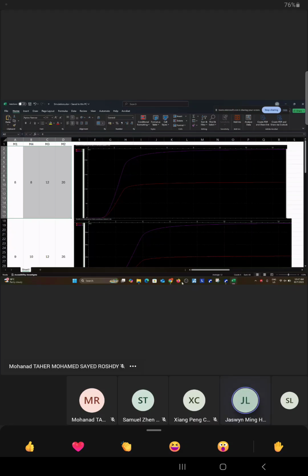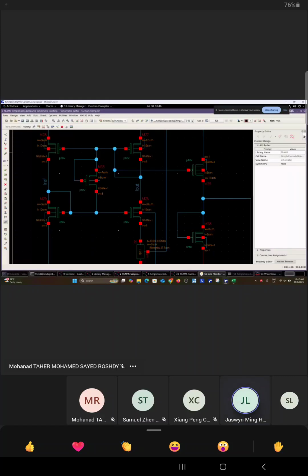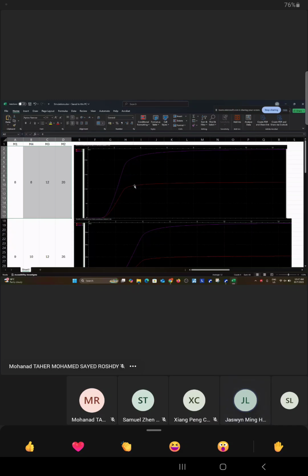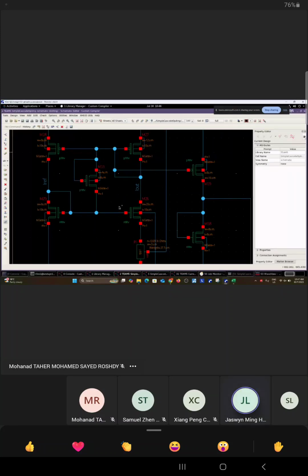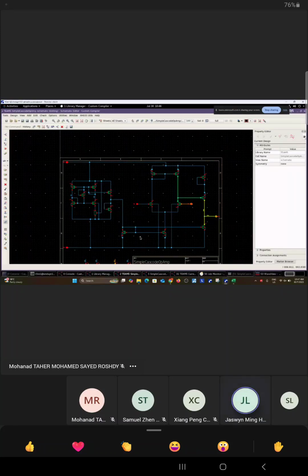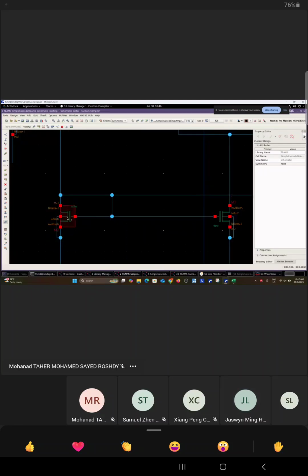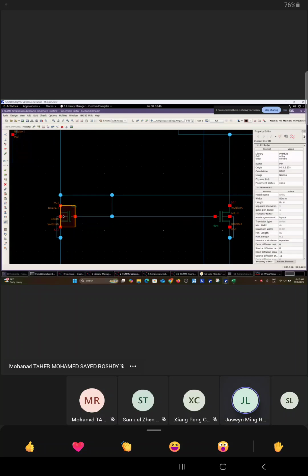Which means that you go to your schematic. They were using this one. We're using like the 20 micro. Yeah, 50 micro seems so unstable. I think you can use a 12.5. This one is good enough, because later on you can go to your schematic. Okay, actually, you zoom out a bit. You go to here. Yeah, your M9. Your M9 is mirrored to M7, right? And then you can see your M7 ratio is 80 to 80. Oh, then it's the same ratio, right?